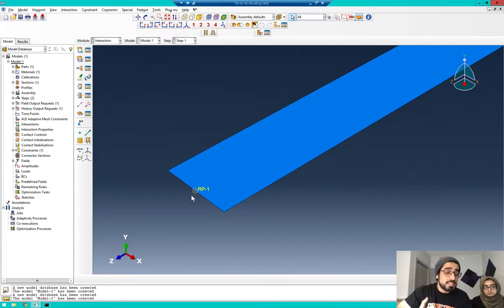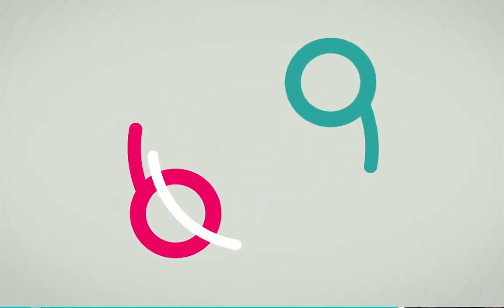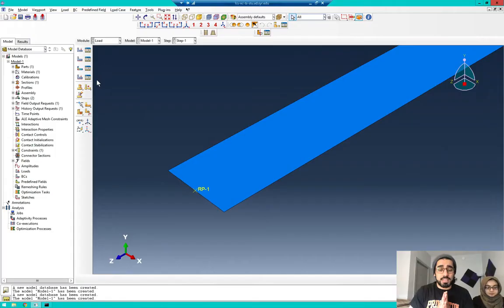Next, we need to assign the loading. We need to apply the loading. Now we go to the loading module, okay? The first thing, now you tell me, okay, I have loading, I need to assign it. What type of loading did I apply when we put the oranges here? It was concentrated, right? It wasn't distributed, it was concentrated, okay? But we said we want to avoid the local stress concentration problem. Here, because this is steel, this is strong, we don't have the stress concentration problem.